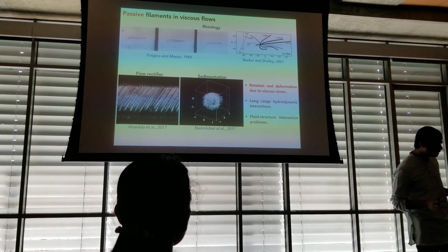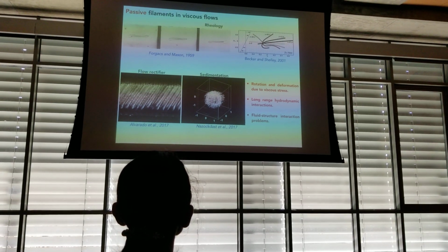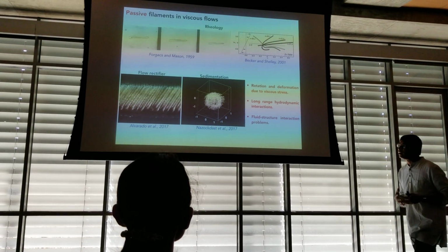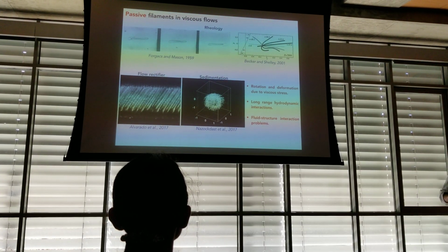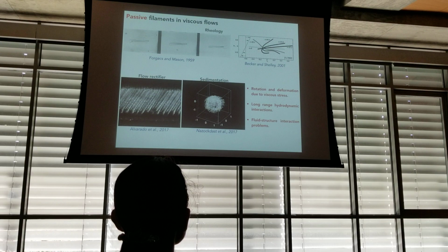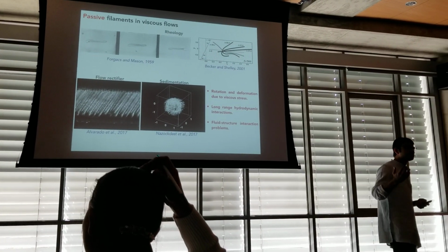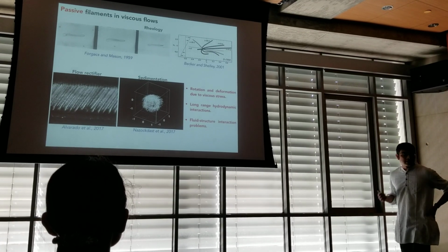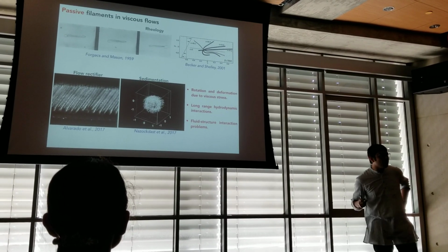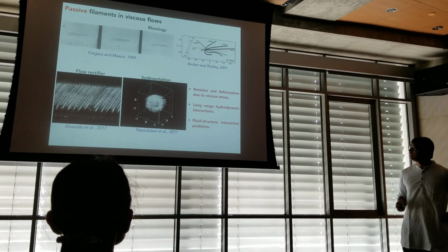So filaments and fibers are actually quite ubiquitous in Stokes flow. Think of complex fluids or non-Newtonian fluids. They're essentially suspensions of long-chain polymer molecules, filaments, and fibers. If you apply a flow, this microstructure can rotate and deform, and this deformation generates additional stresses at the microscopic scale that manifest themselves as interesting rheological properties at the macro scale. So if you're interested to understand bulk scale properties of this kind of fluids, then it's often interesting and important to go back to the micro scale and look at the dynamics of individual filaments.